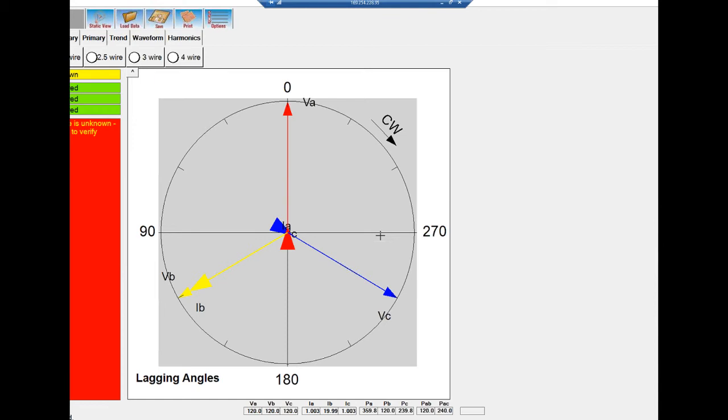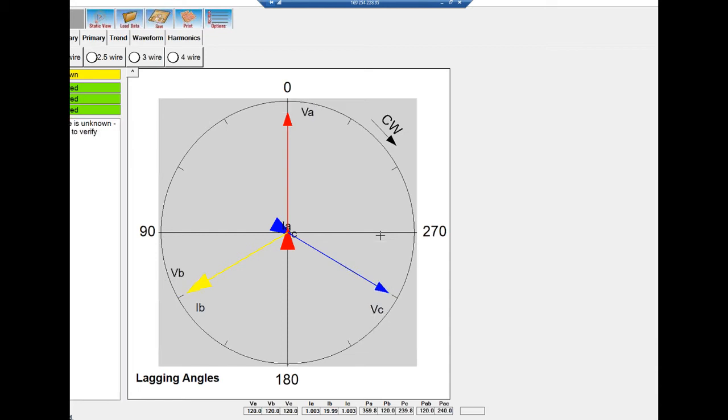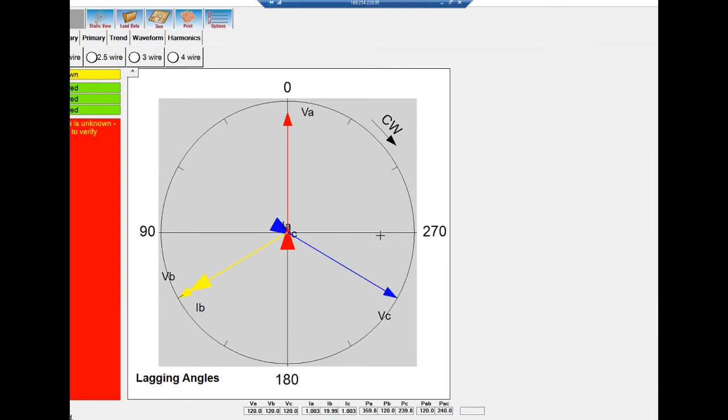The other thing I want to go over is looking at harmonic content as well inside of power quality. Like I was saying, it is very highly unlikely that you will have a perfect sine wave at the site that you'll be looking at. So I want to show off a little bit of what harmonic content would look like inside of the power quality window on the RW, and then what you can do with that and the power of the RW under harmonic conditions. So let me go set up some harmonic content on the site right here behind me. I'll show you what harmonic content looks like on the RW.